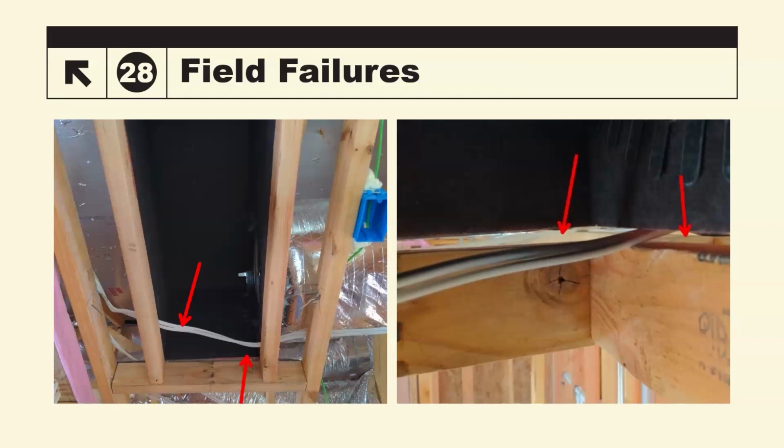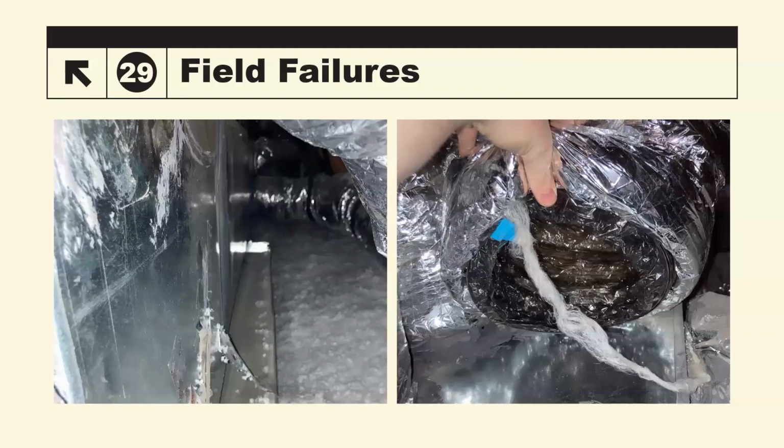So these kinds of things can also add to duct problems in testing. And of course, it also sometimes pays just to give the ducts a little shake when you're in the attic. Though these are probably not intentional, it does happen and things are forgotten. So there's not a collar here. The person put the ducts there, it's supposed to be done, and of course, the collar wasn't installed.